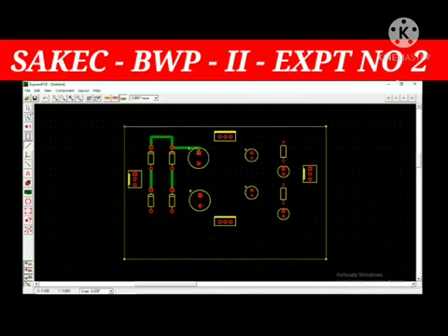Now see, this drill is on track. If this drill becomes big, this track will damage. So in PCB rule, our main important rule is track should not be on the trace. So you have to remove this hole from this trace. For that I will use this option, disconnect trace. I will disconnect from here and I will connect it here.